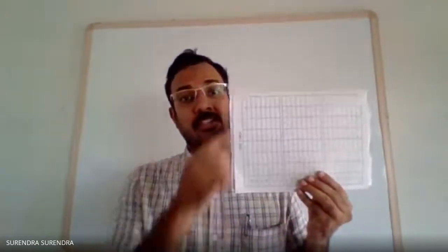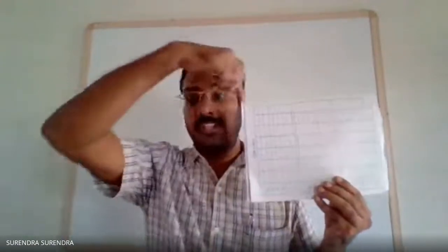If a surface is parallel to one reference plane, it implies it is perpendicular to the other reference plane. So the surface is parallel to VP. When the surface is parallel to VP, we can see the true shape in the front view. In the top view, we can see a line. It is at a distance of 25 mm away from VP, so in the top view, the line is at a distance of 25 mm from the XY line.